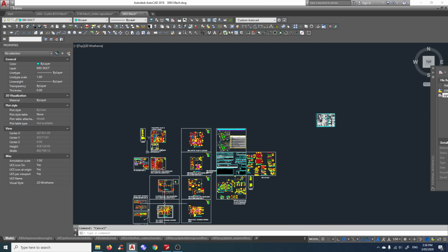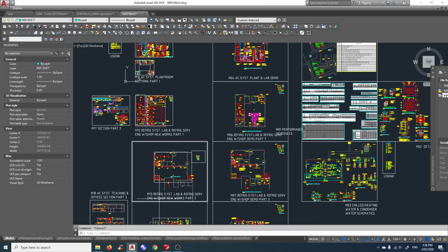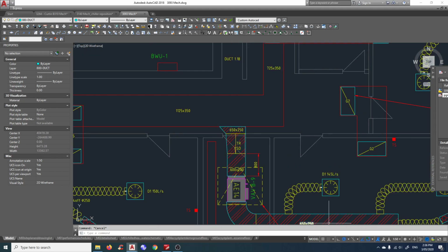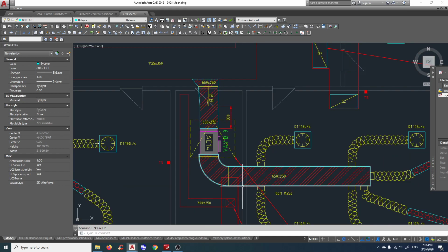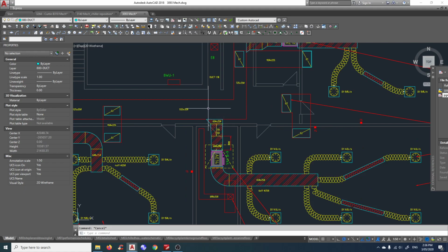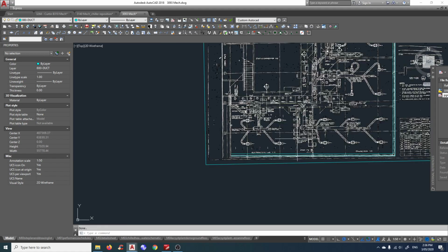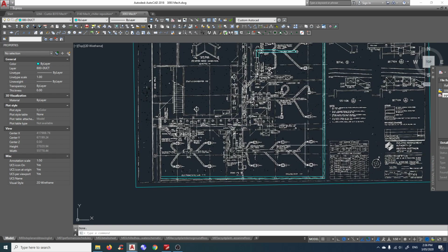But when you draw a new duct on top of that existing duct, such as that, you see here, although there is an insulation on this duct, I do not show it because the heads would be clashing with the heads that I want. So triple line here means 50 mil insulation for the new duct, and existing duct I'll just take the insulation off, means not touching it. So that's how you do your assignment 2.